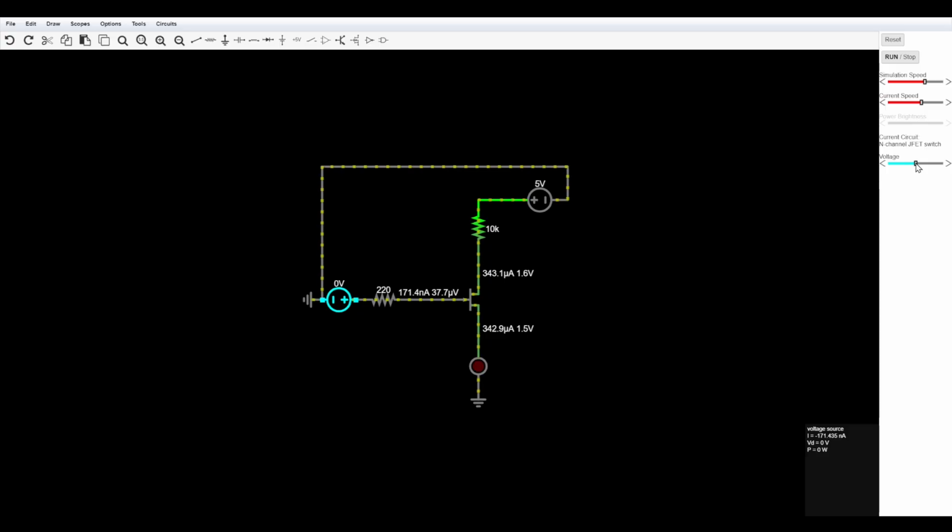Let's adjust the gate voltage up. So yeah, the current's going. Mind you, this is supposed to be voltage controlled current conducting. So at this point, we definitely see the LED at 2.2 volts. We'll keep doing, but notice at 1.7, it's holding pretty steady on the volts. And eventually at 5 volts, we've got 12.2 milliamps and 1.8 volts.